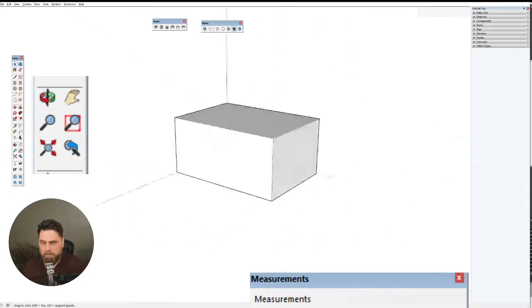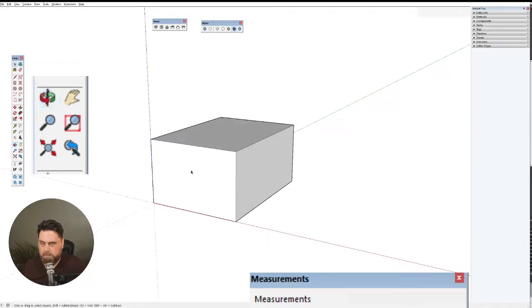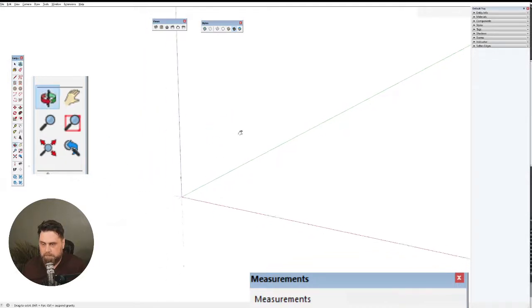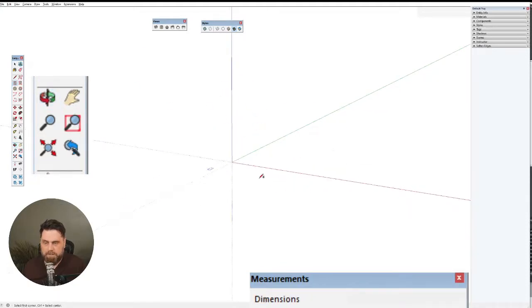Now, I realize if you guys are brand new to SketchUp, even drawing this box might have been confusing. So let me just walk you through that quick so you have something to help navigate through. With the large tool set, we're going to go down here to rectangle, and we're going to click in here, just position your screen so that our axis is right in the center.